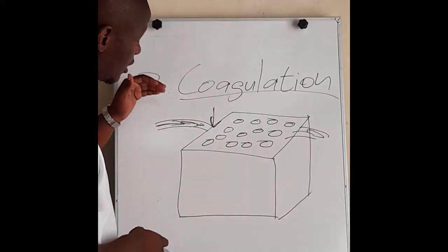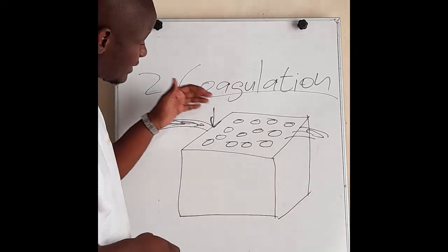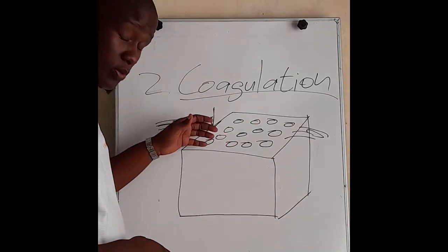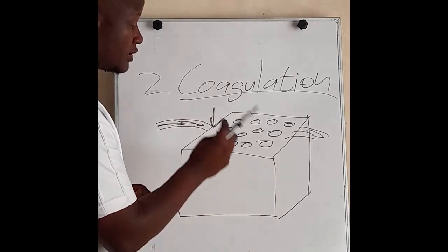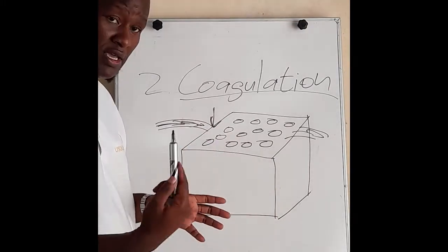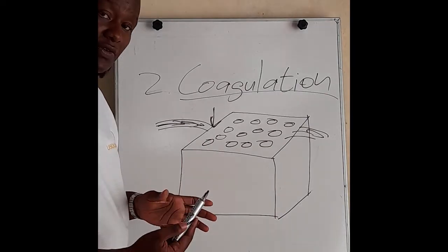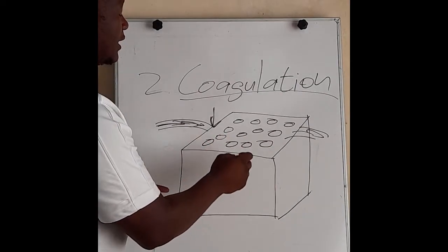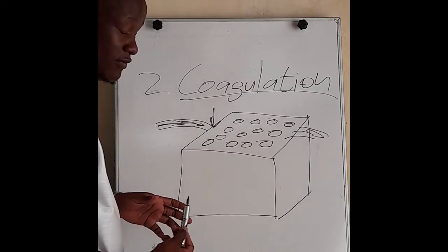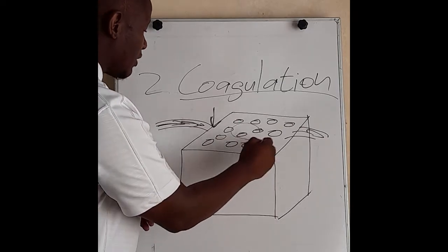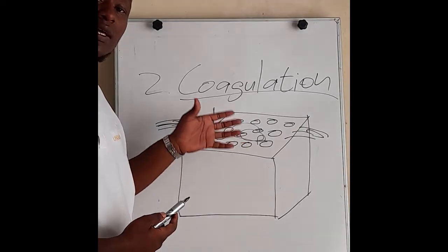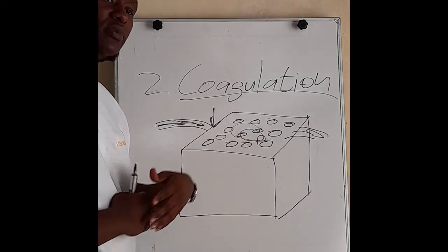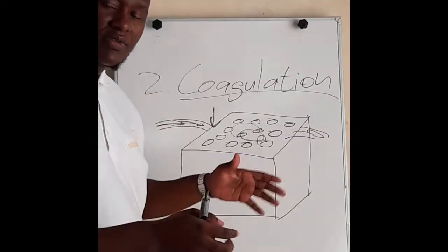As this influent is getting into this basin and being dosed, the velocity of the water in this basin is actually very fast. The reason for the water having a fast velocity is that it is stirred around, so that when you are dosing that coagulant, it's able to be spread all around the basin.